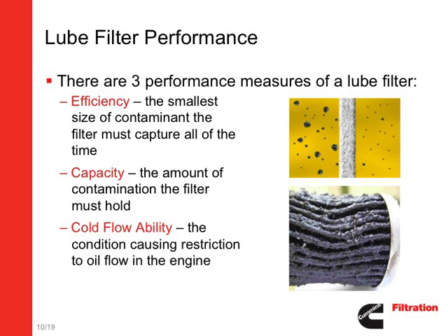To determine the correct lube filter required for your application, you must understand lube filter performance. There are three measures of the performance of a lube filter. The first is efficiency. The efficiency of a filter is the smallest size of contaminant the filter must capture all of the time. Also important is the capacity of the filter, which is simply the amount of contamination the filter is able to hold. The final measure of performance is the cold flow ability of the filter, which is the measure of the restriction of the filter under certain conditions, such as low ambient temperatures.